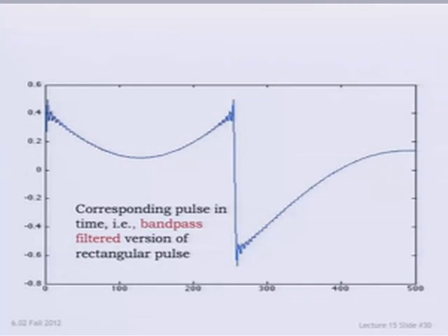Not very good. Because the low frequencies are missing, this thing tends to sag in the middle. It can't hold up DC. And it can't make the very sharp transitions either, so there's a more leisurely transition. But again, this can't stay at that level. It actually asymptotes. So the actual pulse occupies, before it settles, way over the 256 bits that I've allotted